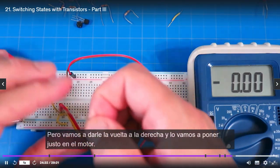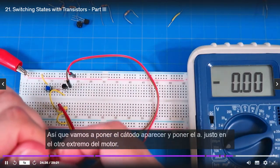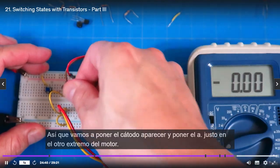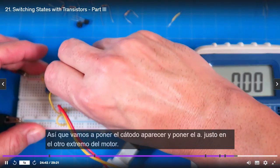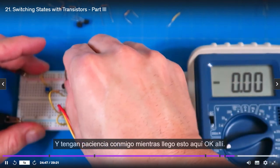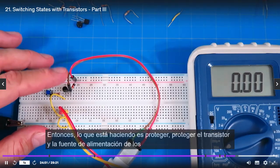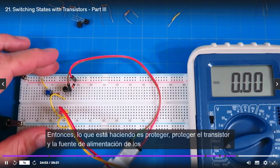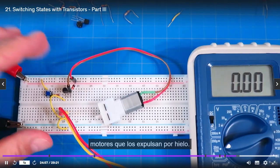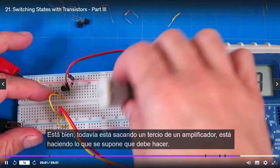We're going to put it right across the motor itself, and here's the motor. So we're going to put the cathode up here and the anode at the other end of the motor, and bear with me as I get this in here. Okay, there. Now that's protecting the transistor and the power supply from the motor's back EMF. The motor will still work. It's still pulling 1/3 of an amp, doing what it's supposed to do.